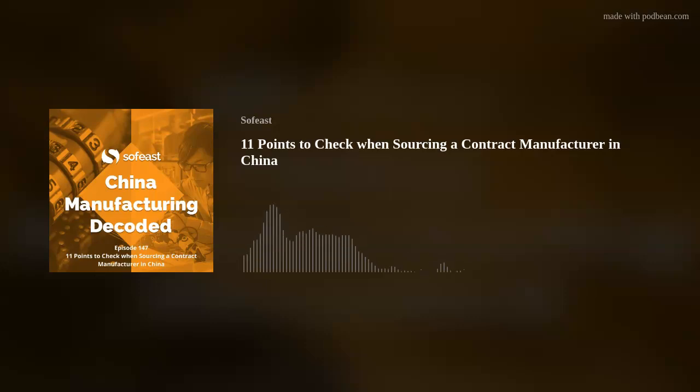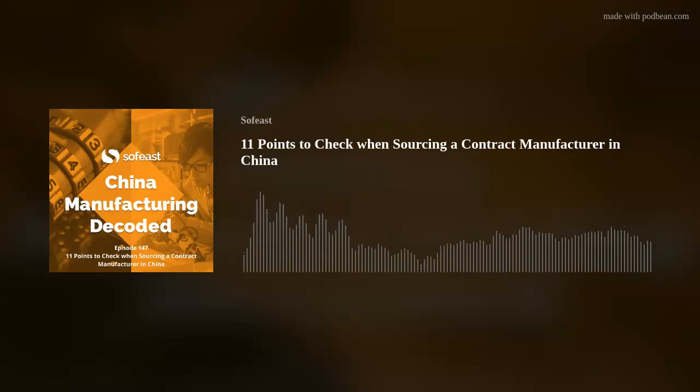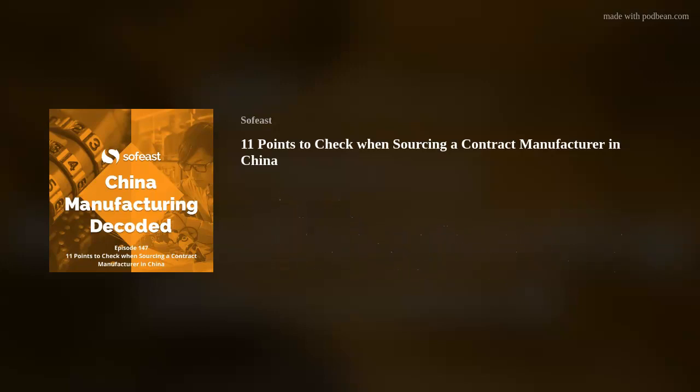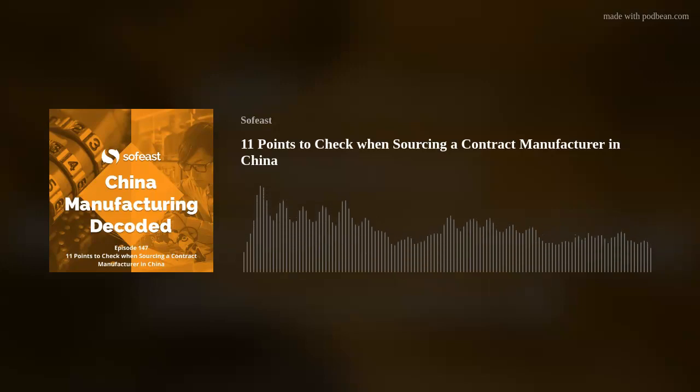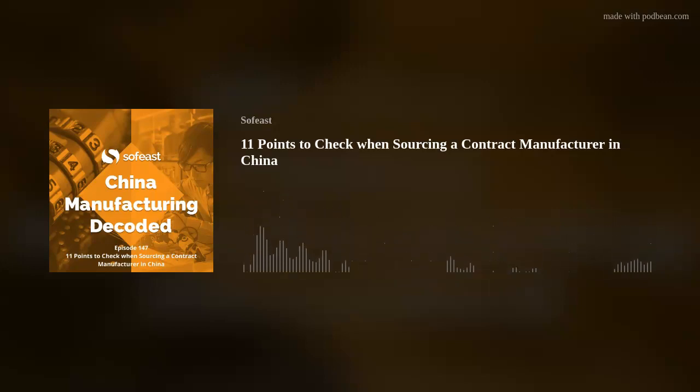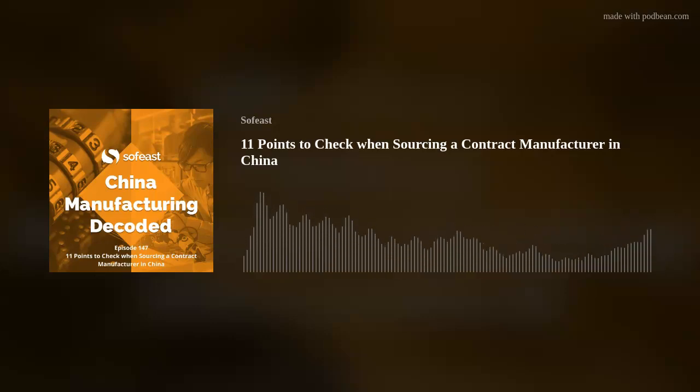Versus some other places where things are much more flexible, they have process engineers and they have a certain process to make their lines more flexible, let's say, right? And the line leaders have their checklist and are used to it, and they switch from this one to that one, and they make sure that there's no material from the previous one still on the line, and they have to make sure that all the work instructions change and so on and so forth.